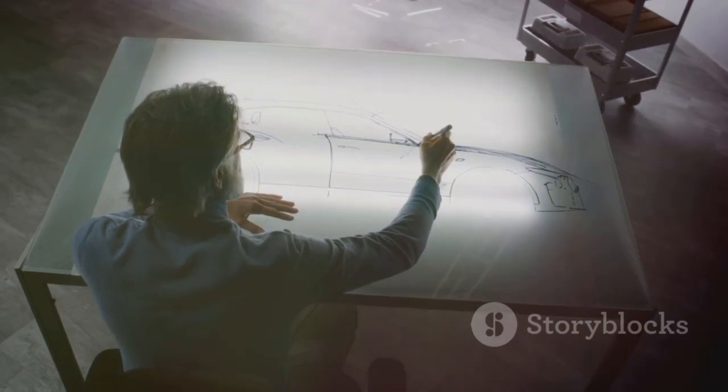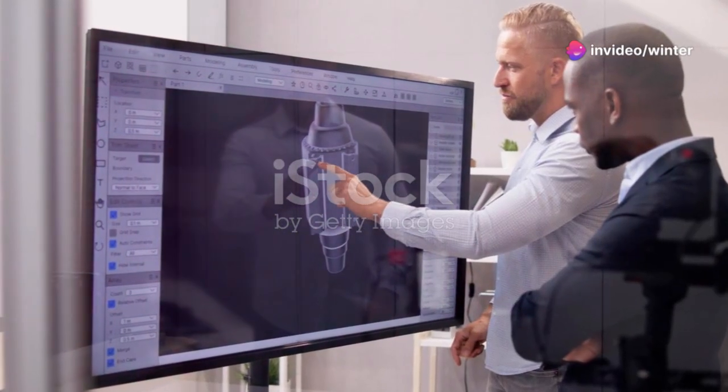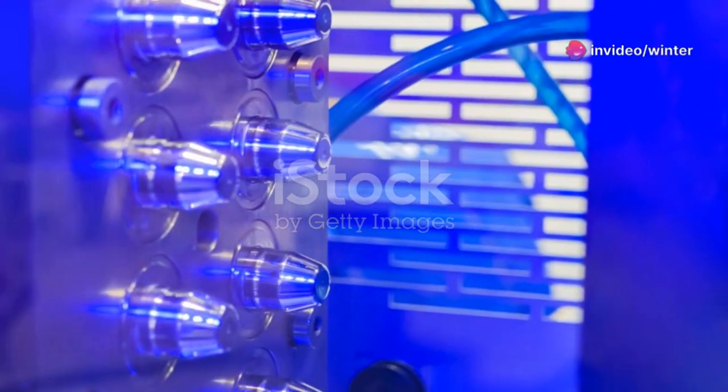Minimize side actions for a simpler, more reliable, and cheaper mold. Scrutinize every feature. Eliminate unnecessary complexity. Great designers avoid side actions whenever possible. That's how you keep costs under control.